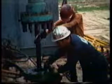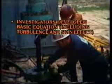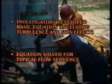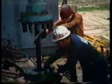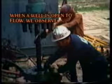In order to gain this additional information and accuracy, investigators have developed the basic equation that represents the radial flow of gas into a wellbore. In doing so, they have included terms for turbulence and skin effect. The equation has been solved for the type of flow test that are possible on gas wells. One such well test is to shut a well in until its pressure has stabilized, and then open it to flow at constant rate and observe its pressure behavior.